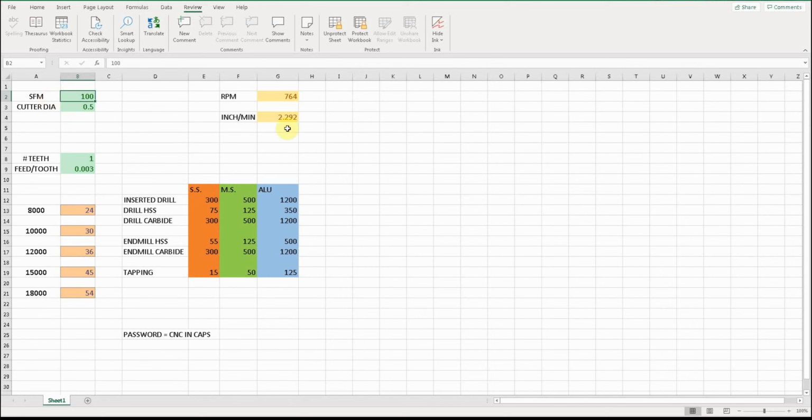Okay, I know I'm running my inserted drill in 300 series stainless, 303, 304, 300 RPM. That's a 2-inch inserted drill. You say it has one tooth and you go 3/1000ths per tooth. Well, there's your RPM, 573. And there's your feed, 1.7 inches a minute.